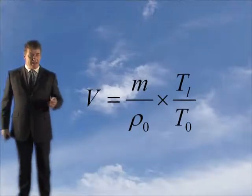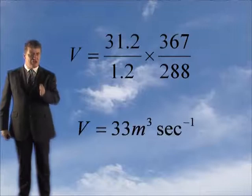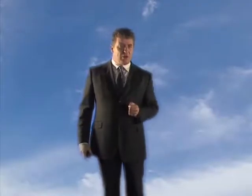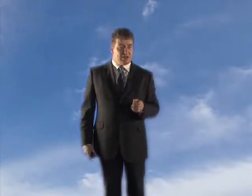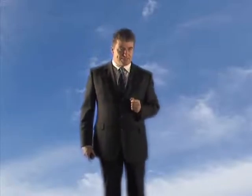And this is a formula. V equals M divided by rho 0 times TL divided by TO. If you'd put them in, you'd have got a volumetric flow rate requirement of 33 metres cubed a second. So that's how much smoke, volumetric wise, we have got to extract. We've got 4 fans rated at 10 metres cubed a second, giving us an extraction rate of 40 metres cubed a second. So we can be confident that the smoke will be extracted.